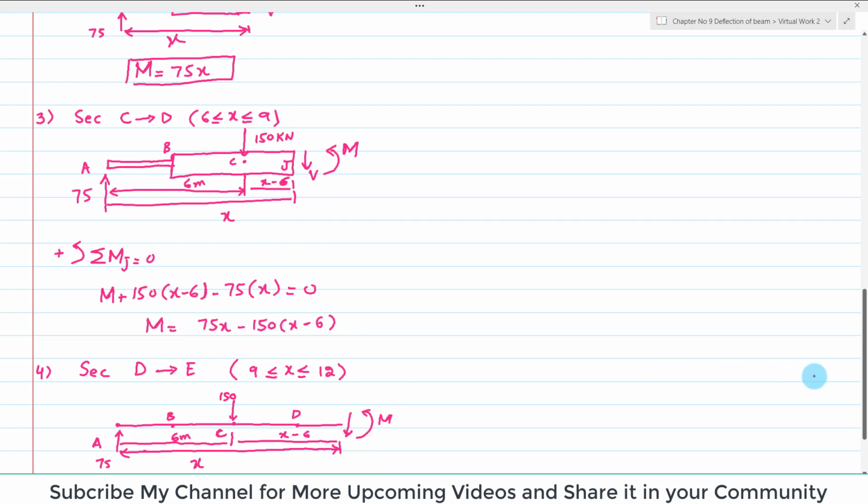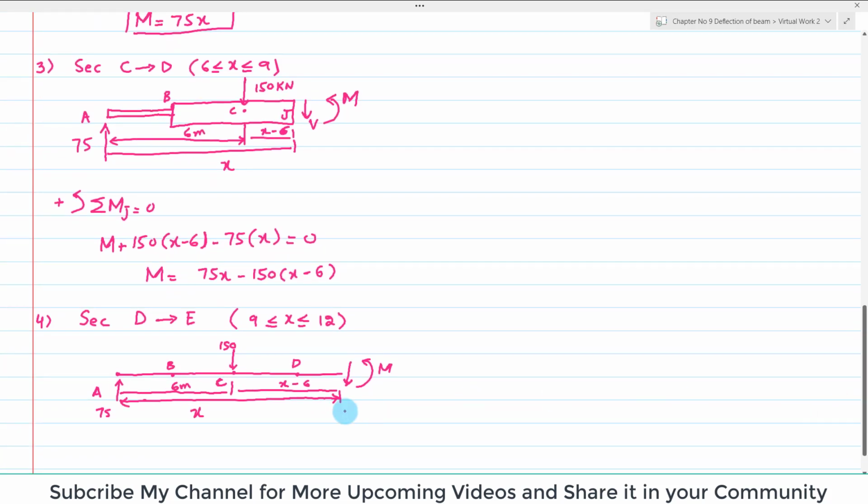So when you apply the moment equation, you will get the same bending moment for section D to E. The bending moment will be equal to 75x minus 150 into (x minus 6). So again, note them and write it in the table.